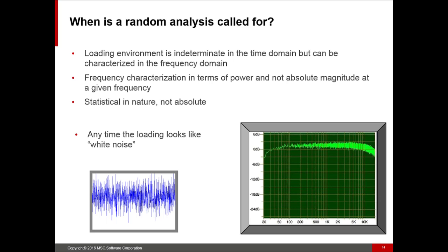What we will actually say is that 68% of the time, we should never go up to this value, be it displacement, stresses, or something like that. So this is getting into statistics, so we'll usually do some multiplications on top of that to say, well, 99% of the time we're not going to see values that reach that high.